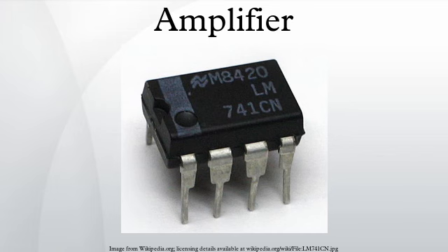Amplifier types. Amplifiers are described according to their input and output properties. They exhibit the property of gain, or multiplication factor that relates the magnitude of the output signal to the input signal. The gain may be specified as the ratio of output voltage to input voltage, output power to input power, or some combination of current, voltage, and power. In many cases, with input and output in the same unit, gain is unitless. The four basic types of amplifiers are as follows.